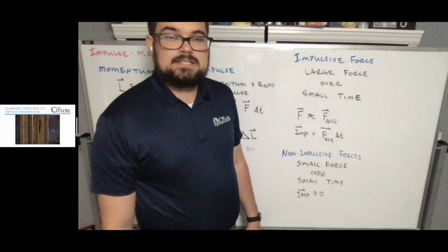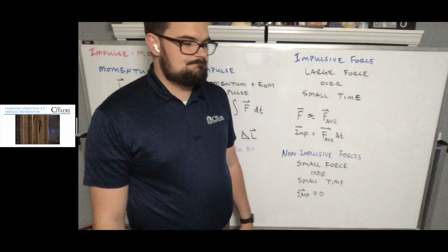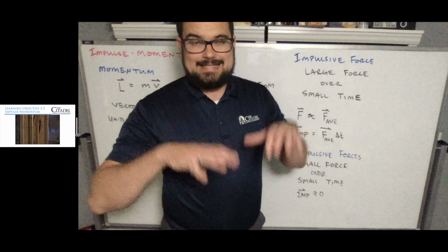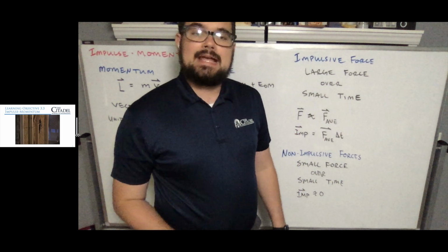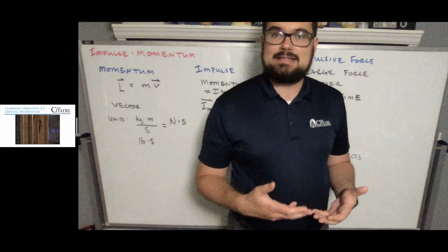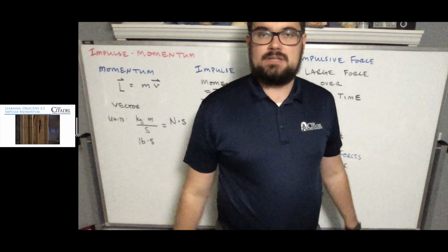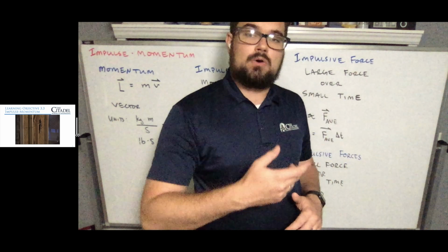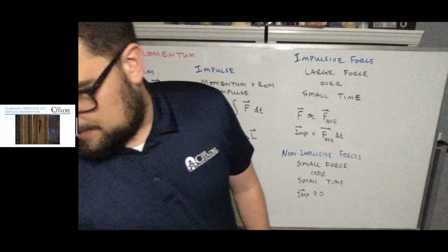Another example of this impact impulse: I have a colleague who had a boss who would actually measure the density of soils that were compacted using a golf ball. He'd bounce the golf ball, and he had a good sense for how much rebound was needed for his materials to be properly compacted. And it turned out that the more time, because of the deformation of the material, the less that the ball would bounce back up. And so he knew that he needed to do more compaction. So that's another example of impulse momentum.